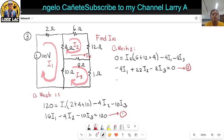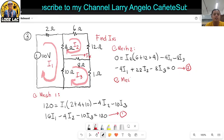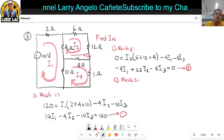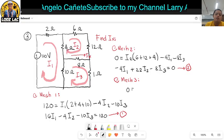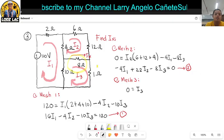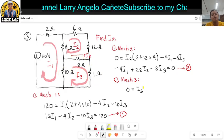We're almost done with the three equations. Solve once again for the third equation, referring to mesh 3. There's no voltage source in mesh 3, so 0 equals I3 times the sum of all resistors. For this mesh there are 8, 1, and 10, so add the three: 8 plus 1 plus 10.